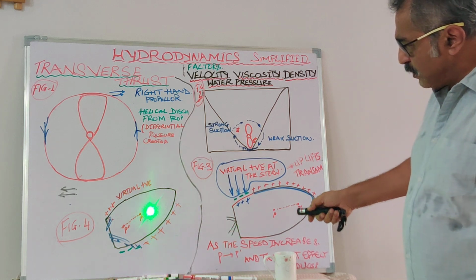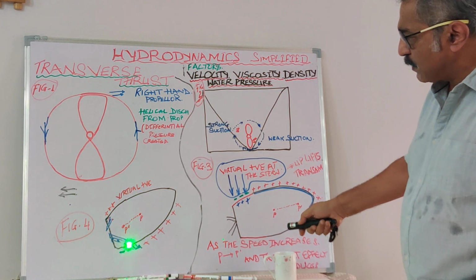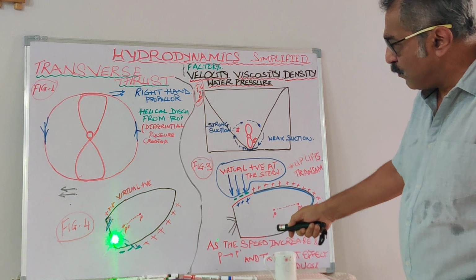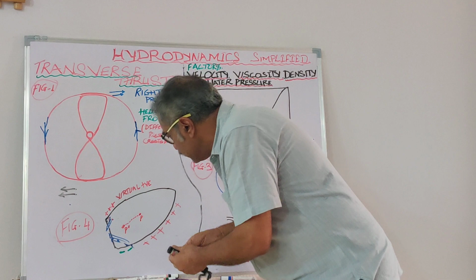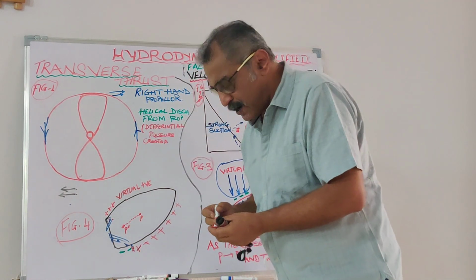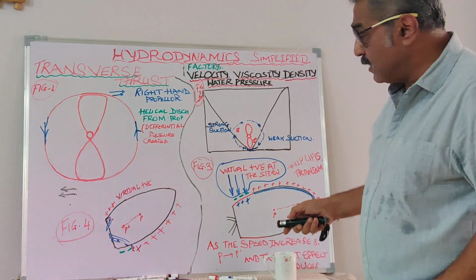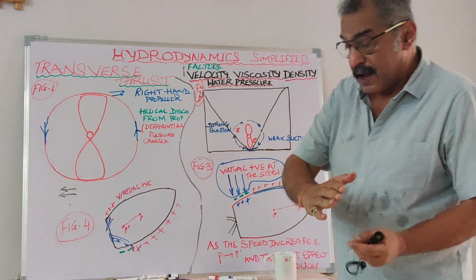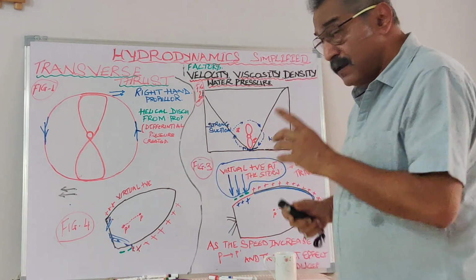Because of the underwater volume of displacement, the positive forces are at least up to 1/4 of the length from the stern. To make it more clear, I depict it over here. The positive forces experienced by the vessel going astern are approximately 1/4 of the length from the stern because of the underwater volume of displacement. As the vessel is canting to starboard, the water is getting filled up.